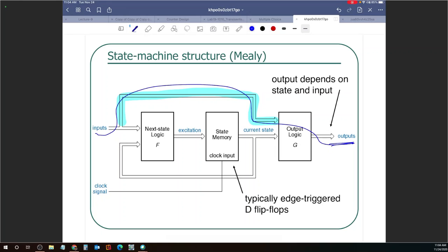Is this unnecessary for human operated? Well, that depends on the application, right? And that also depends on how much you are willing to invest in terms of space and cost for a design. I'm going to later show you that Mealy designs can be simplified and they are much more effective in terms of cost than Moore design. So there are benefits of considering a Mealy design, other than just the speed of the response. In some cases, you would want to have that speed.